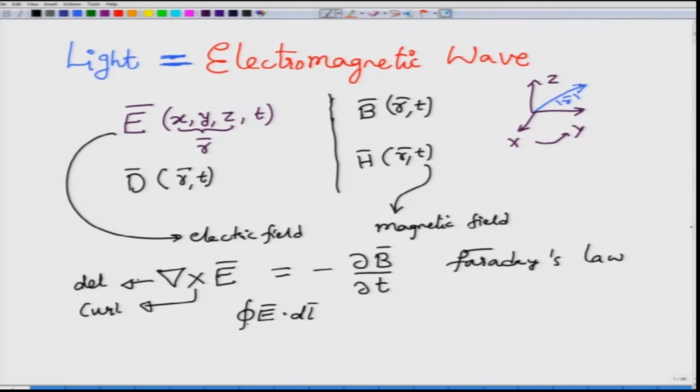Whatever quantity you get when you integrate E dot dl over it is called the EMF, and sometimes this EMF is denoted by the letter nu. This denotes an EMF over the entire loop. In the static case, when there are no magnetic fields involved, this EMF over the entire loop will be equal to 0.